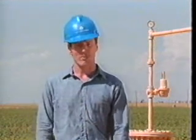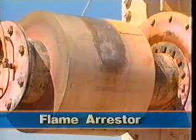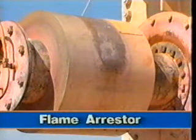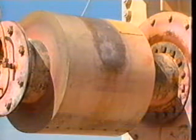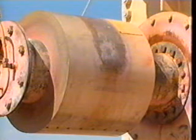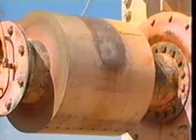In order to operate properly and safely, every heater treater is equipped with safety devices and monitoring features. A flame arrestor fits on the front of the firebox. A series of aluminum vanes placed closely together disperses heat generated in the firebox into the air. This reduces the possibility of fire spreading outside the vessel.